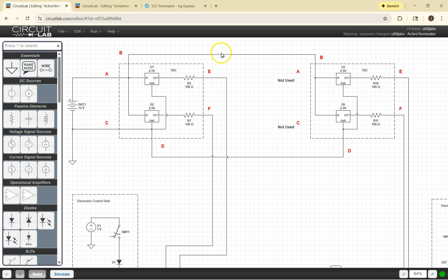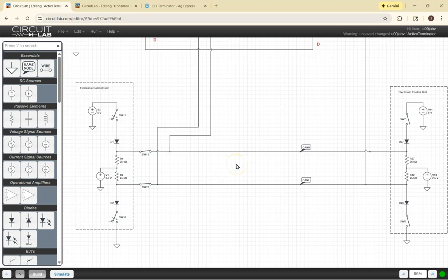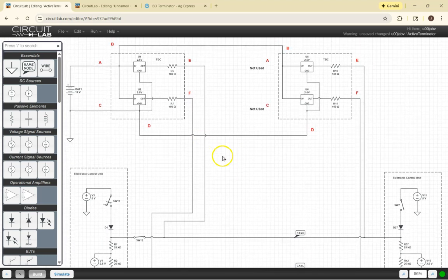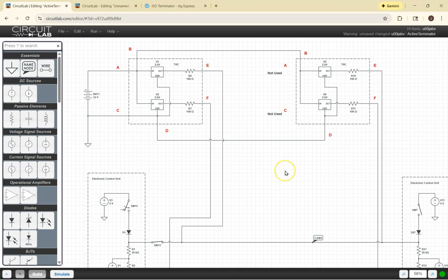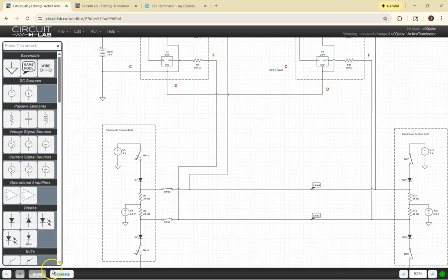As most ag techs know, this power and ground are routed together, twisted in a quad pair throughout the entire machine. So CAN high, CAN low, and this power and ground are twisted together. This provides excellent immunity to something called electromagnetic interference, as do these devices. But you can see that these devices are doing the same thing as what the passive terminator does, but they do it better.